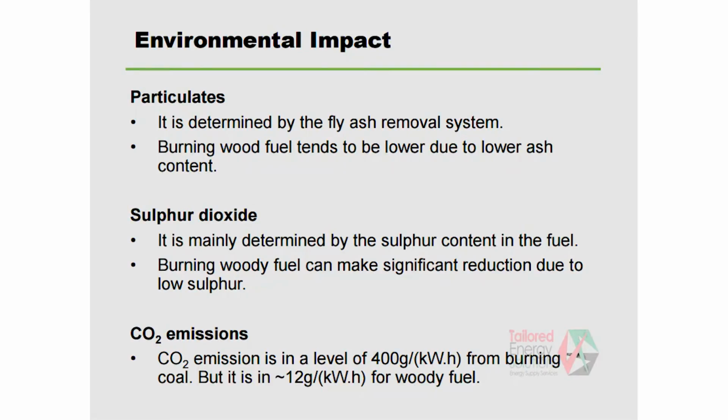On the environmental side, burning wood waste is going to be better for particulates, mainly because of the lower ash content. Sulfur dioxide is also going to benefit. CO2 emission from burning coal is around 400 grams per kilowatt hour. But for burning wood, because it is considered renewable, it is around 12 grams. That's much, much lower. That's why I want to go that way.